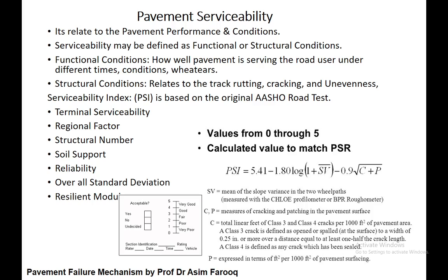Pavement serviceability index is very important to evaluate the functional and structural condition of the pavement. The functional aspect tells us how well the road is actually serving under different conditions. When we talk about the structural, we refer mainly to the loading criteria, so we relate the term to rutting, cracking and unevenness.